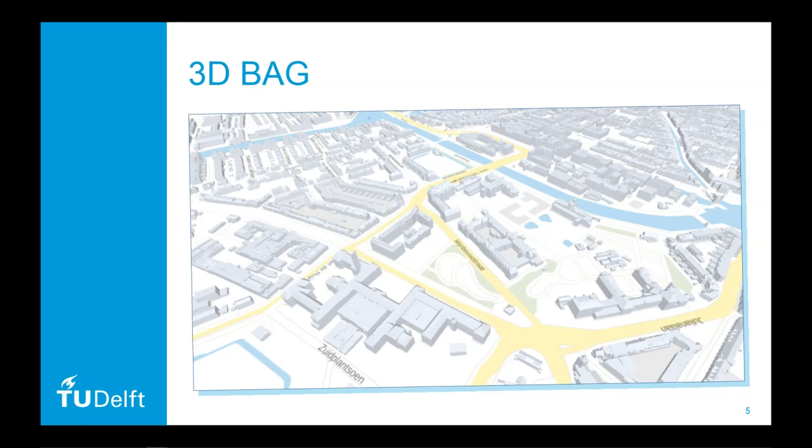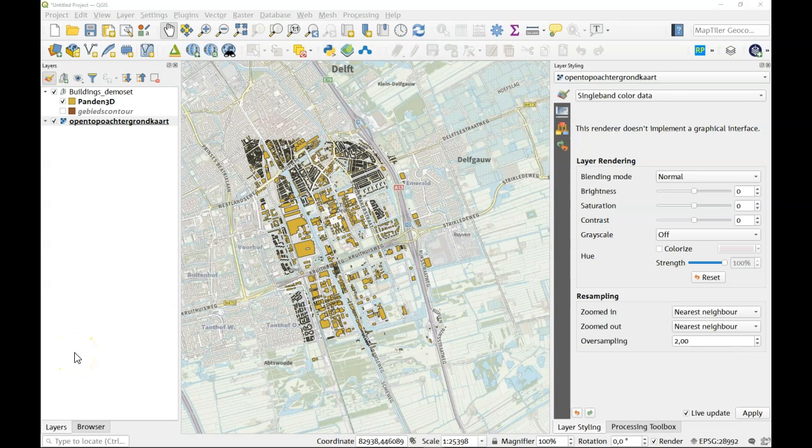They have different models for different purposes. In this example, we're going to use the download options for buildings with Z values. There's not just one Z value, as on each roof there are a number of measurements taken. We're going to settle for the height value of the 95th percentile of these measurements, which gives a result that can be used for various purposes. Here you see the sample data set that we share with you.